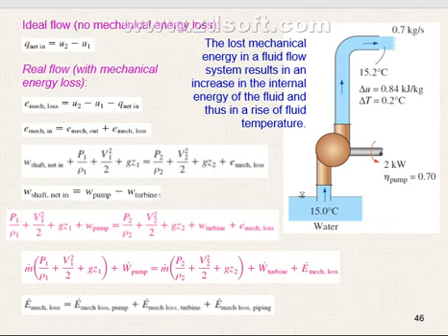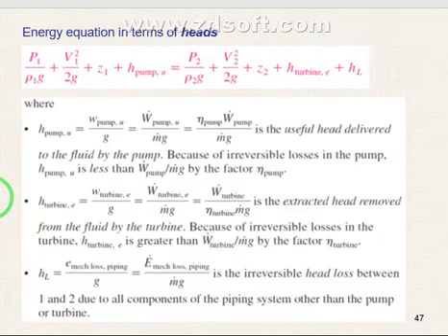Okay, so guys, when we have this mechanical energy and multiply it by mass, we will have the work and the energy needed for the system. So this is just a derivation. This is the summary here. This is the conclusion. I need you to understand this. It's very similar to the Bernoulli equation, but we added a turbine here, and we added a pump here, turbine, and HL here.